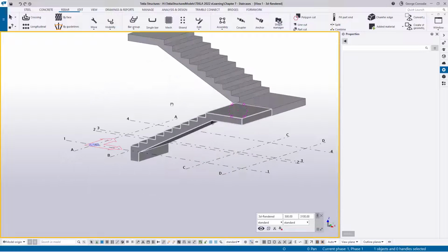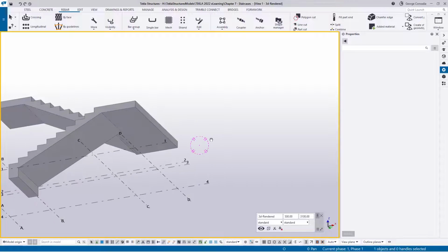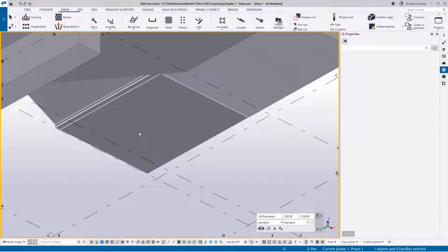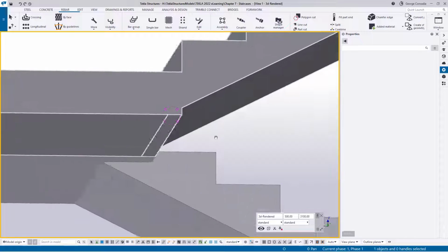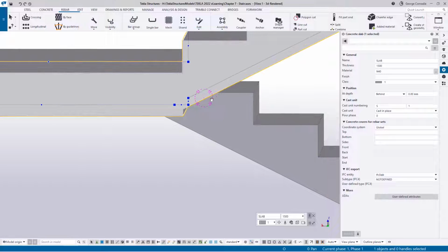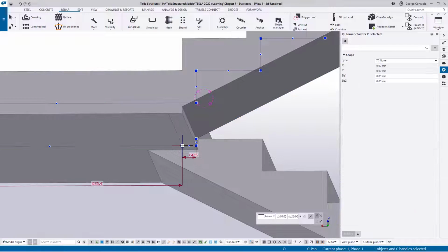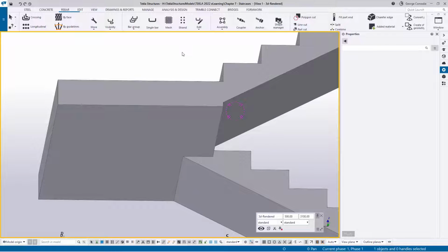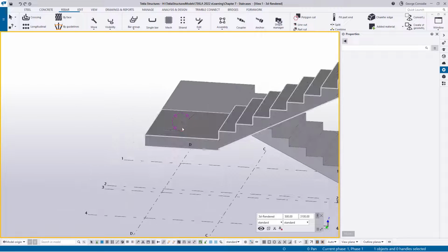If you look at it, if they're all the same materials, Tekla pretty much shows it monolithic, and it's a good result, the way that Tekla actually does this. It's pretty good. I've just noticed there's a little line there. All you have to do is take that little note and delete it, and it cleans up that face nicely for you. There was an unnecessary note there, but it really does a good job if you can do it that way.